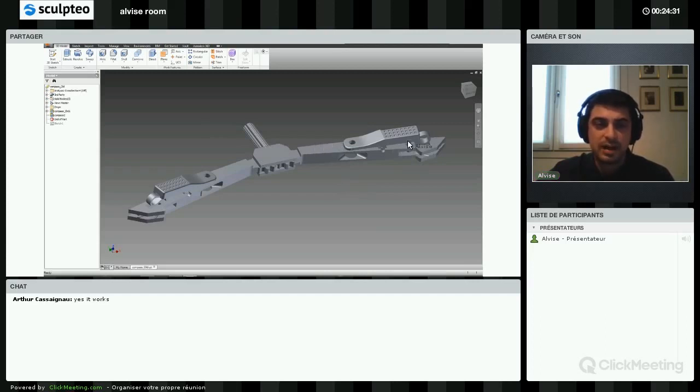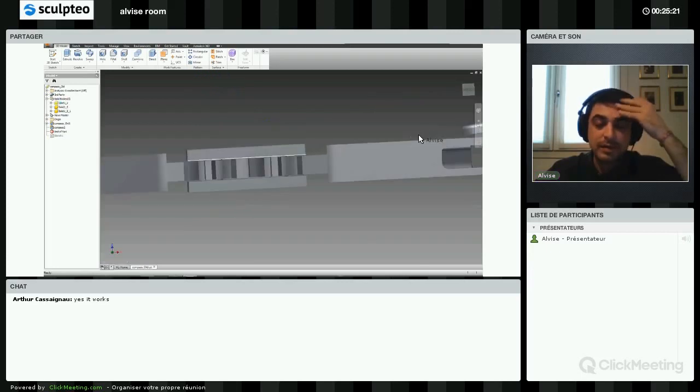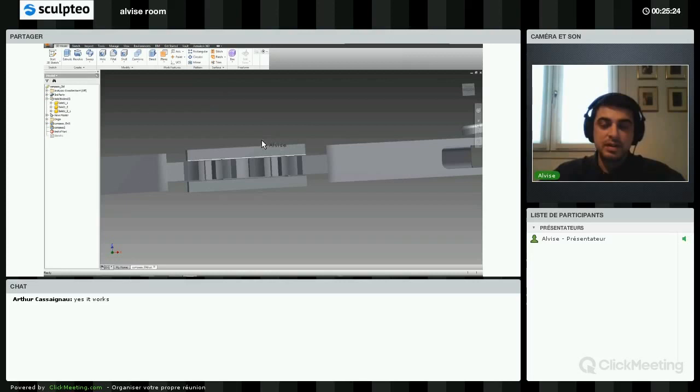So as you can see here on the left, on the stack solid bodies group, if we select them, there are three parts. They are moving in relationship with each other through these gears in the middle, and then this middle part is together. I'm just hiding the visibility of this part, so you can see the gears. So there is space between these parts, and there is space between these parts and the third body. This is a proper clearance, but the powder between these parts couldn't be removed by our technicians.